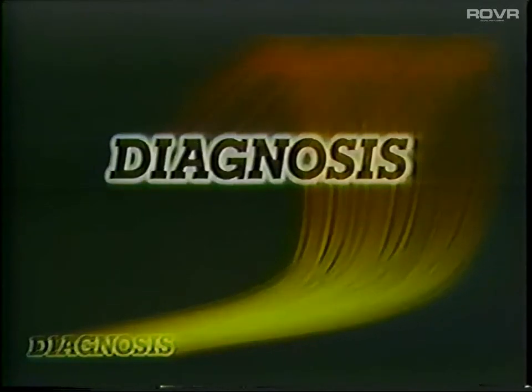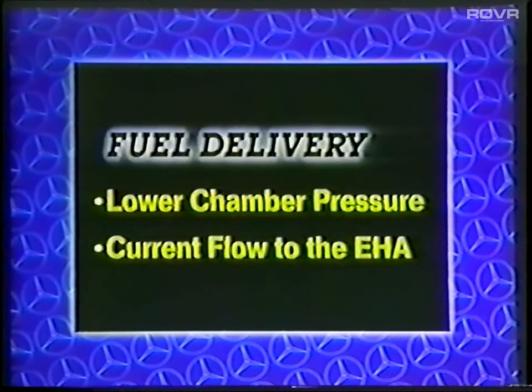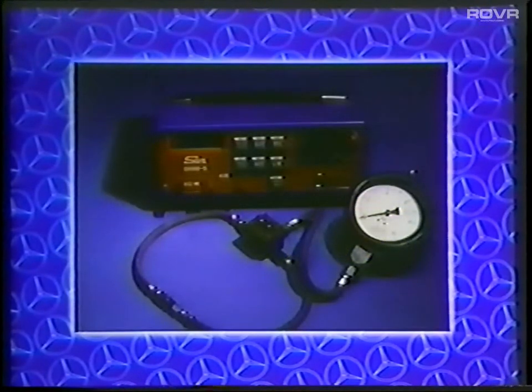As we have explained, fuel delivery to the engine is dependent on fuel pressure in the lower chamber of the fuel distributor, and it is the current flow to the EHA that regulates this fuel pressure. Therefore, to perform diagnosis, a fuel pressure gauge and a meter capable of reading milliamps are required. The pressure gauge is a Mercedes-Benz special tool, and two versions have been made available since the introduction of CIS. A multimeter of known quality, such as the Sun DMM5, is the second requirement.